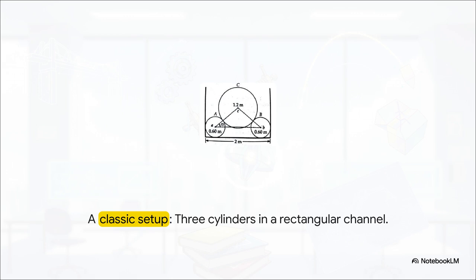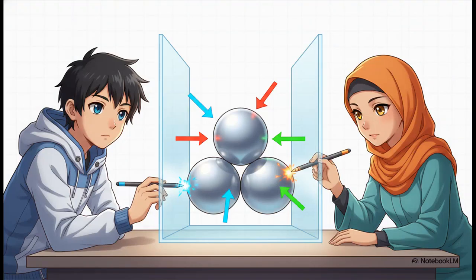But remember our strategy. This is not one giant unsolvable mess. It's really just a sequence of 3 very simple free body diagrams stacked on top of each other. The big secret here is just analyzing the forces at their precise points of contact. So, cylinder A touches the left wall, the floor, and cylinder C. That's 3 reaction points, plus gravity.